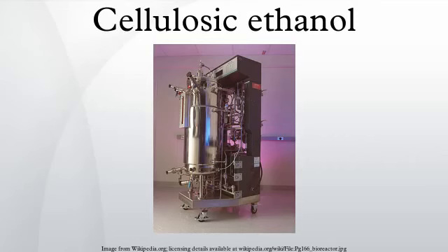Gasification process. The gasification process does not rely on chemical decomposition of the cellulose chain. Instead of breaking the cellulose into sugar molecules, the carbon in the raw material is converted into synthesis gas, using what amounts to partial combustion. The carbon monoxide, carbon dioxide and hydrogen may then be fed into a special kind of fermenter. Instead of sugar fermentation with yeast, this process uses Clostridium ljungdahlii bacteria. This microorganism will ingest carbon monoxide, carbon dioxide and hydrogen and produce ethanol and water.